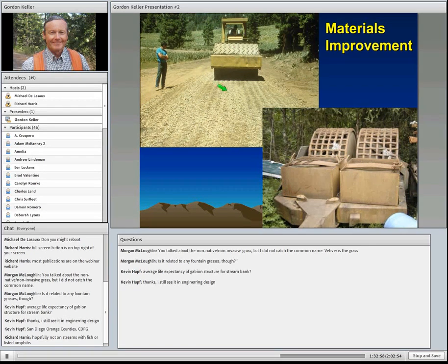Say this was, I think, an andesite that was not extremely hard, so we could break it down, and then you have something you can live with a little bit better. It's not as good quality aggregate as a good hard base rock or a surface rock, but it's inexpensive because it's close to the site. So we use marginal materials a lot on low volume roads, and I think they're very appropriate because they can be very cost effective.